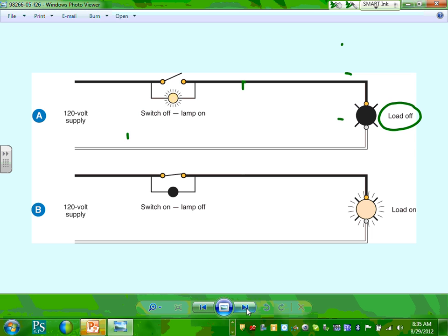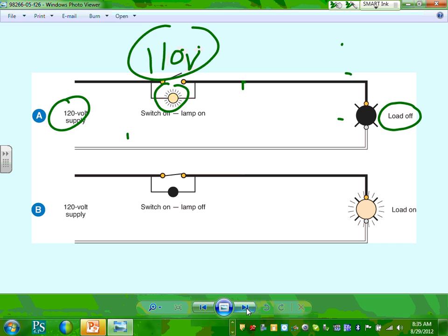There's a tiny little resistor inside the switch. You wired it? So you don't see it. You just bring in and out, and when you wire, you don't even mess with it. The way it works, when you bring the voltage 120 here, it puts this one and this one in series. When you flip the switch open, it puts the two in series. This is a very fat, fluffy, big resistor, so if the voltage is 120, I'm just going to throw out a number, it takes 110 volts across it. And the other 10 volts goes here. Do you think the 10 volts will be able to energize this boy?